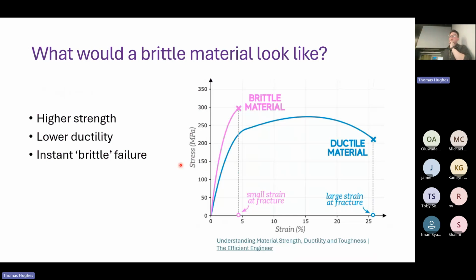So let's say we have a reactor part, any ideas why we'd like it to be ductile rather than brittle? I mean, brittle materials are generally stronger, right? Yeah. I mean, the main point is they fail slower. If our reactor can just smash at any moment and we can't catch that and replace the part or stop the reactor, then we're in trouble. So we don't want brittle materials in our reactor. We want nice ductile materials that can absorb a lot of punishment.